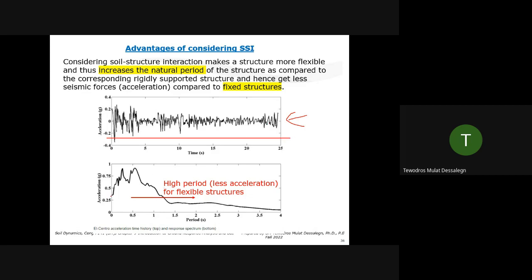From the response spectrum, like in a pseudostatic design case, you get the fundamental period of your structure, you pick the corresponding acceleration, and you can use that in a simplified version. And we say to account for higher modes, you can multiply by 1.5. And in the rigid zone, this is a high period, or in this case, then it's very low. You can even get flatter.